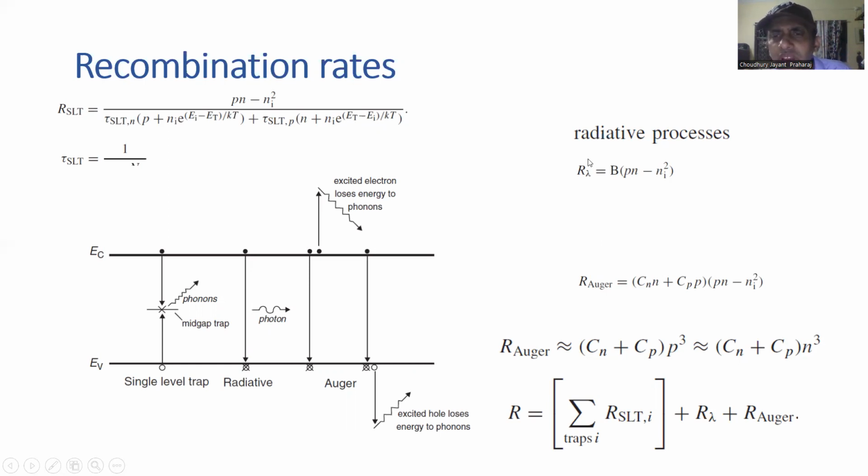In the radiative recombination process, the electron in the conduction band recombines with the hole in the valence band and emits the energy as a photon again. In the solar cell, this is basically a re-emission of an above band gap photon.